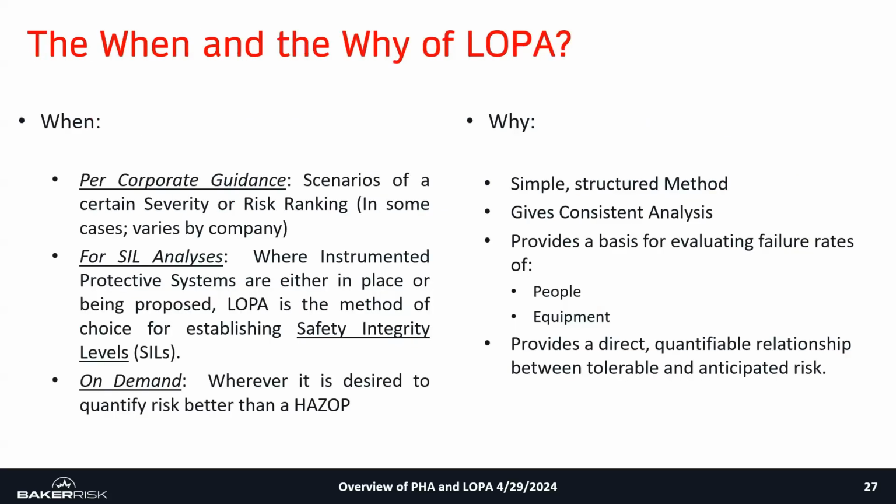So when should you do LOPA and why? Really, this question of when is dependent upon your specific company's requirements. But what we've seen is a lot of times companies will have corporate guidance that says, if your scenario reaches a specific severity or consequence threshold, you need to do LOPA. Or there's some instances where companies say, okay, when your PHA identifies the need for a safety instrumented system, then you would need to do LOPA, and that would be helpful in determining the safety integrity level needed for that safety instrumented system.